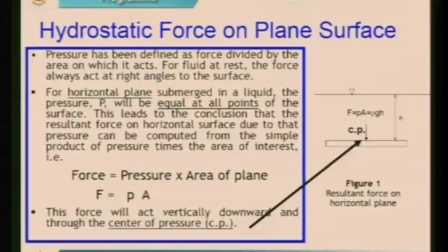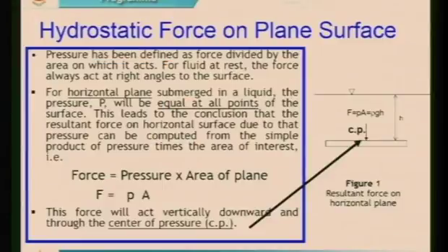Is it okay? So I have introduced two things so far. One is the total force F, and the next point is where this F is acting. It is acting at the centroid of that particular plate, which is nothing but the center of pressure. Is it okay? We would like to know this for many combinations, we will see to it.